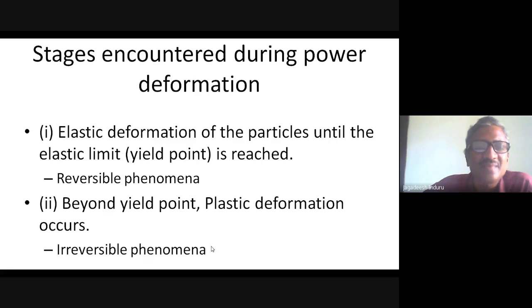Most of the time, in size reduction we employ a cutting mechanism so that we make them broken. And you know that fibrous materials are very tough to get compressed, and with impact too, they will not get much broken, but with a cutting mechanism, they will irreversibly be turned into a smaller powder.